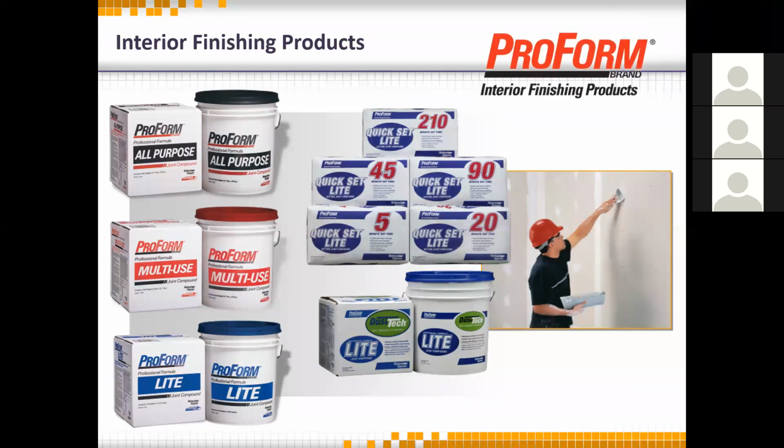These are our mud products, and their difference primarily is one's pre-mixed and one is dry. The one on the right has a chemical curing system. The one on the left dries by evaporation. So if you've got conditions with humidity and temperature where it's going to take longer to recoat the product you're using on the left, then you may want to use the quick set, which has other uses as well, but it can speed up the time that you need. The Dust Tech on the bottom right is a special product that as you sand it, that dust falls to the ground instead of being released into the environment to get into your duct systems.